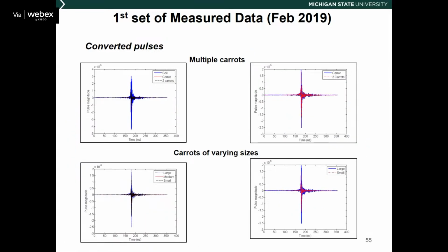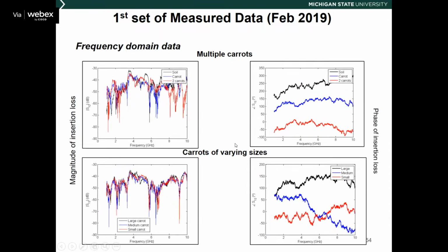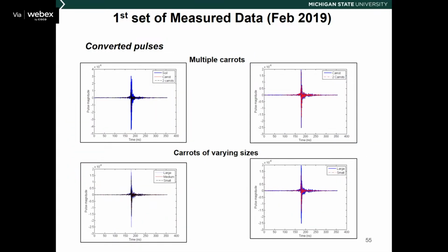Of course, you can convert this into the time domain, because everything we measured using the VNA is in the frequency domain. That's a little bit easier to do. Of course, you can also have time domain microwave measurement, but that would be a different instrument. So we measure everything in the frequency domain, then convert it into the time domain using the inverse Fourier transform. You can see the signal is hard to differentiate in the time domain, but if you apply time reversal,